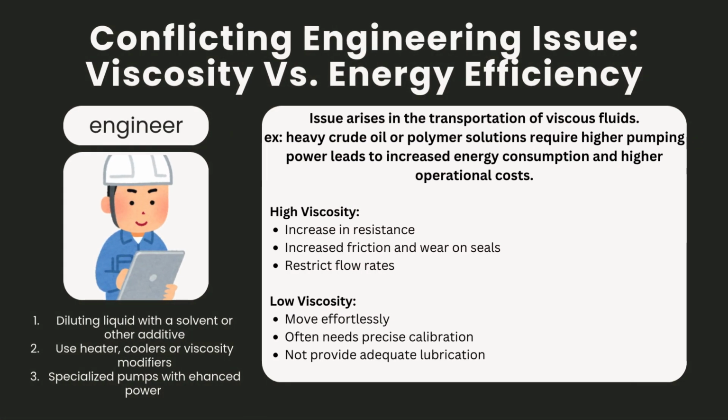A common engineering issue arises in the transportation of viscous fluids. For example, heavy crude oil or polymer solutions require a higher pumping power, leading to increased energy consumption and a higher operational cost. For a high viscosity fluid, it will increase resistance, require more force, and increase friction and wear on seals, potentially causing leaks. And high viscosity can restrict flow rates in pipes or other components.